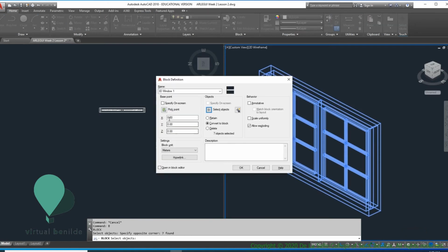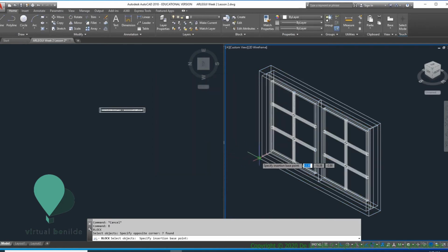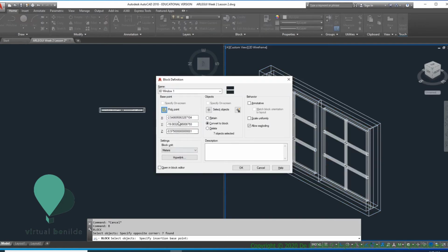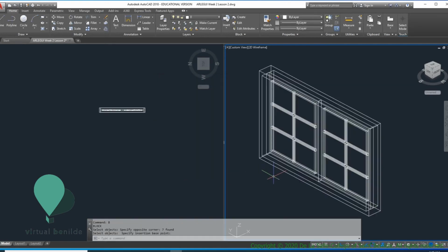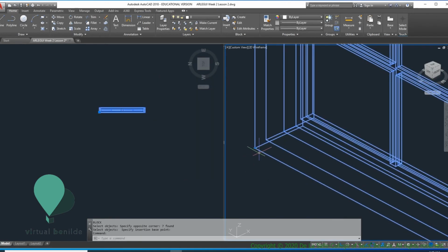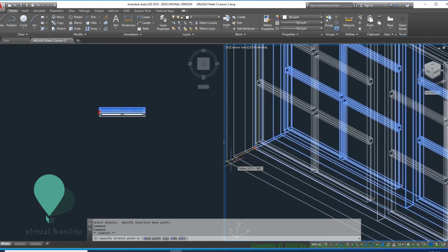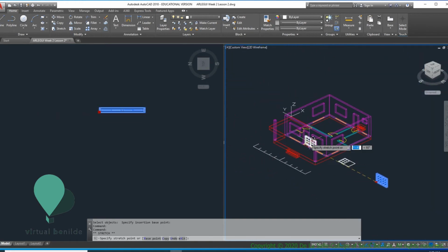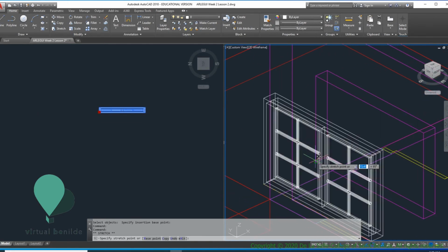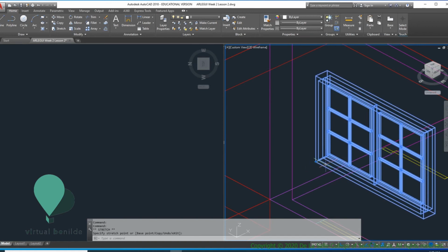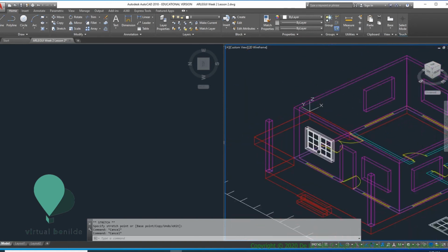When selecting the objects, enter once, and I'm going to pick my point where my pick point is going to be. There you go, and click. So if you click onto this, it's already a block, and your pick point was the one that you designated. So you could easily move this by just pressing that knob and just pressing it over there. So it's in place now.